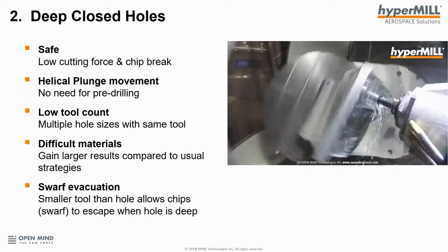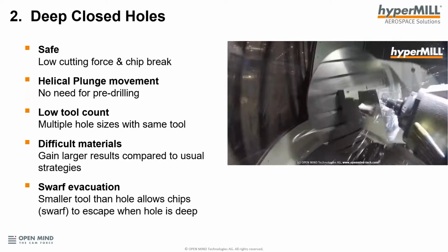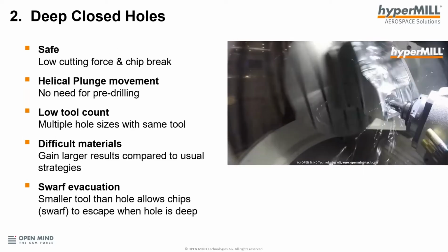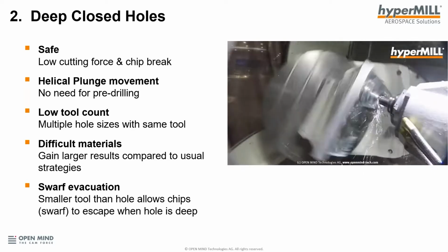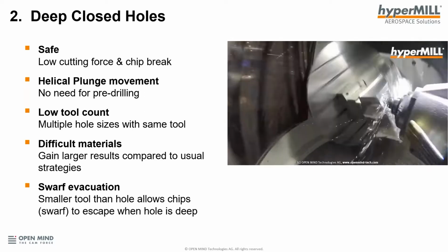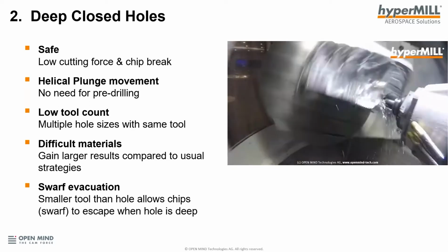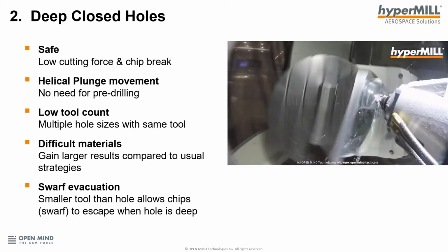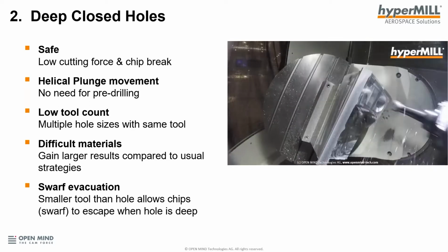The nice thing here is that, of course, you could punch a hole into this pocket with some sort of U-drill or drill type approach, but this usually puts quite high forces on the machine tool. So with these setups, this is quite a nice stable process.